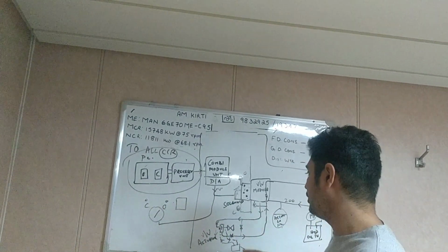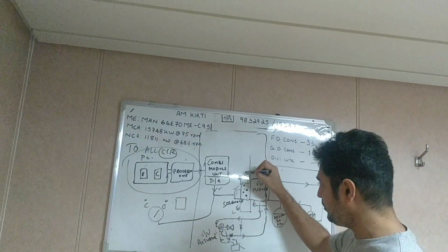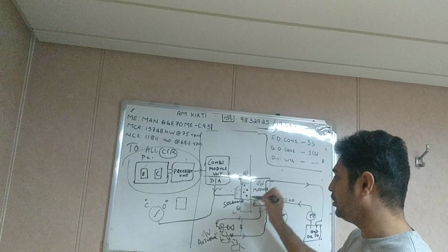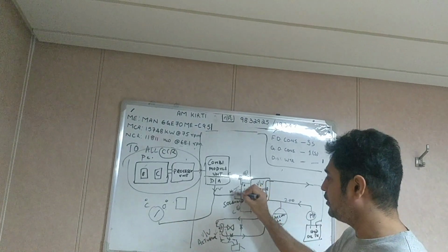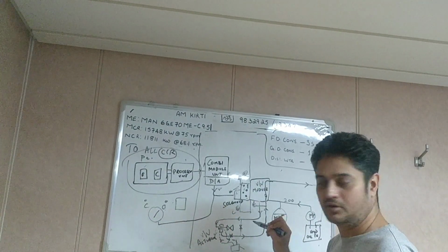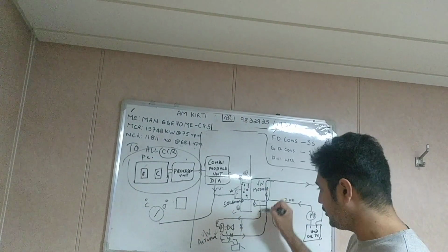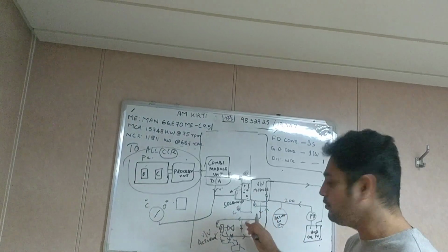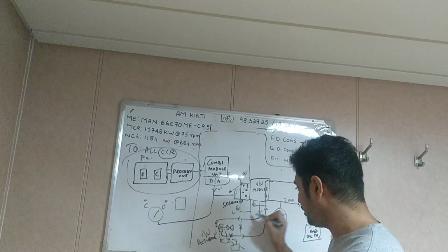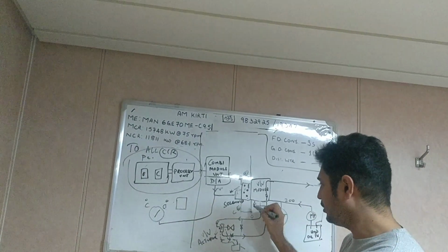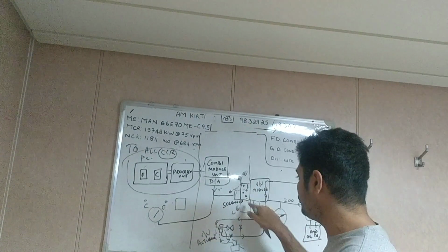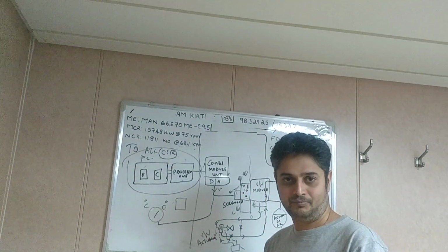In case manual operation from here is not happening, and the solenoid is also not energizing, then you can change the solenoid. Now the solenoid is getting energized, but here there is no response. There is no flow here. Basically you want the line to flow. You should have pressure in this line if you give the command. Suppose this is for open. As I told you, you have given the open command, but this line is not getting pressurized, which means this valve module block you have to replace.